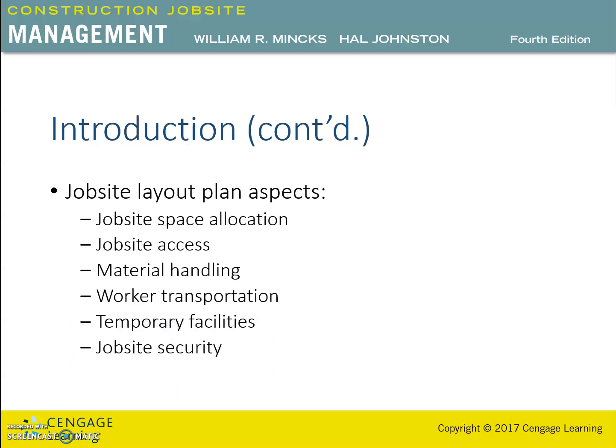Job site security is also included in the job site layout planning. It includes temporary fencing, guard dogs, security patrols, electronic alarm systems, and watchmen. Signage and barricades are required for the protection of the public from the construction hazards on the job site.